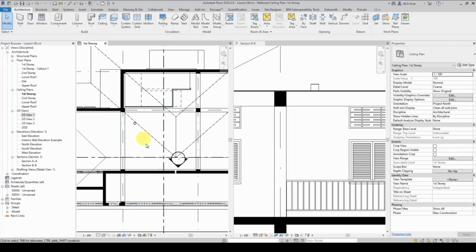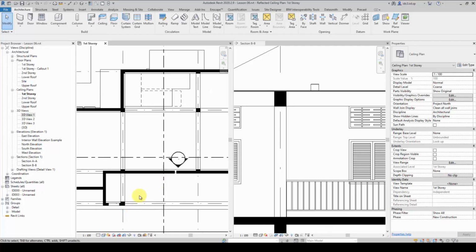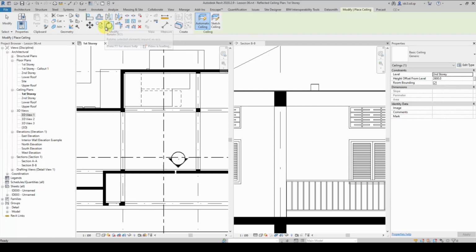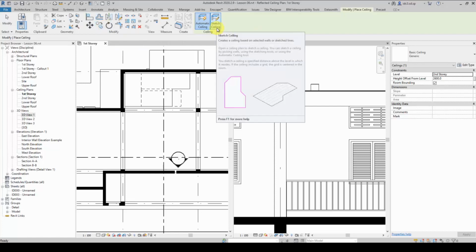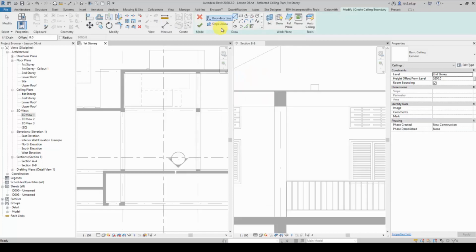At 2.6 meters it seems a little low. Let's maybe try 3 meters for now. At 3 meters ceiling height, I'm going to put it there for now and click finish. Let's take a look and see what we've got. You notice right now we have created a ceiling. So how do we make sure we know we have created it?